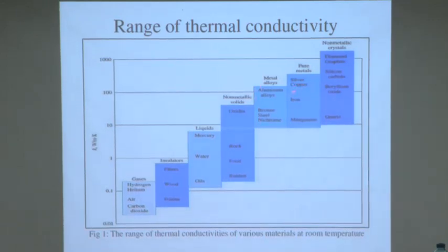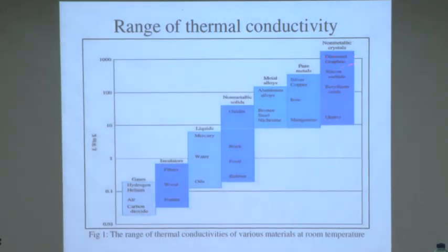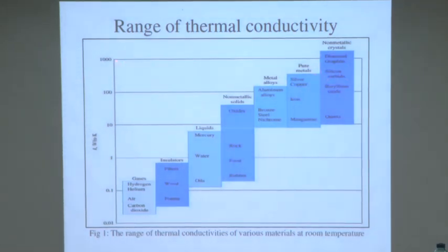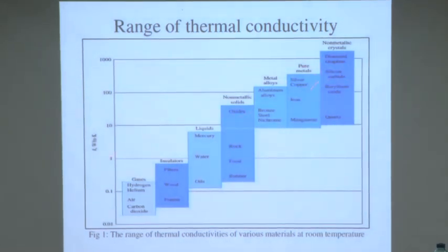Copper is one of the very good heat conductors, whose thermal conductivity is somewhere near 400. And you see those non-metallic highly ordered crystalline solids, that is diamond, graphite, silicon, quartz, their thermal conductivity is even up to 1000 watt per meter K. They show such high thermal conductivity.